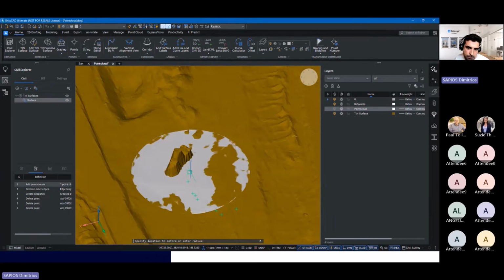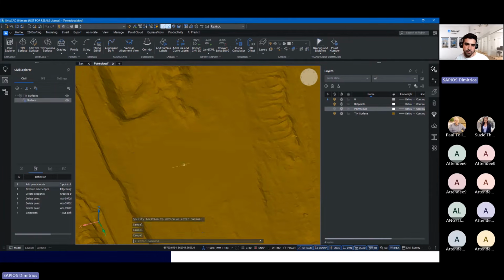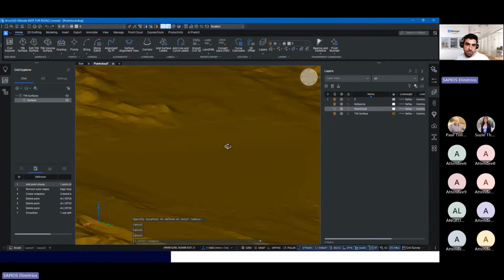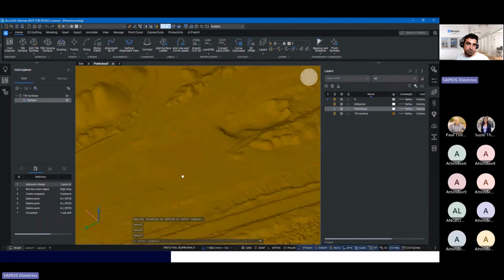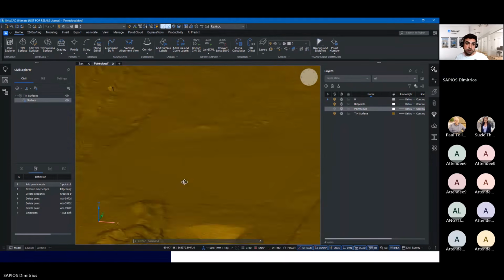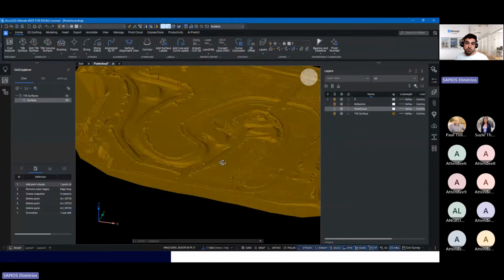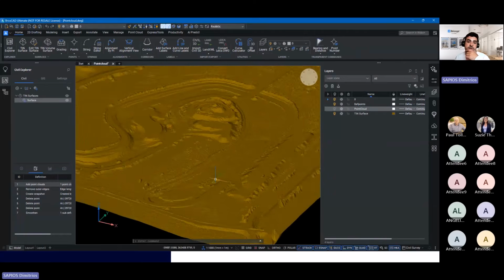So if I completely include this deformation inside the circle and just click on it, it will smoothen it and get rid of all the unwanted points at once. We can of course play around with the radius to make it as good as we want. And there you go. We just fixed the irregularity.